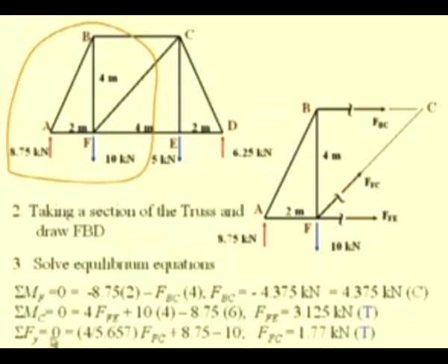The third equation, we can take either a force summation about x axis or a force summation about y axis. Here we have taken the force summation about y axis and we have equated it to 0. From geometry we get the direction cosine of this force FC.